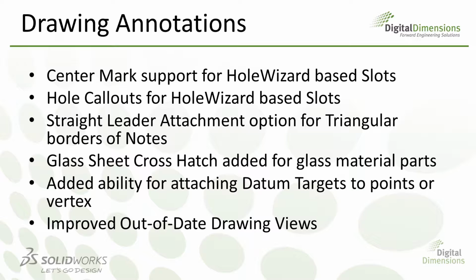And finally, they've added some further capabilities for out-of-date drawing views. Specifically, when you make a change in your model such that the drawing needs to be rebuilt, but you don't want to pay that rebuild penalty, SOLIDWORKS is now not going to obscure the drawing view from your ability to edit the drawing view. So you'll be able to add notes or whatever else needs to happen, and then when you're ready you can pay that rebuild price.